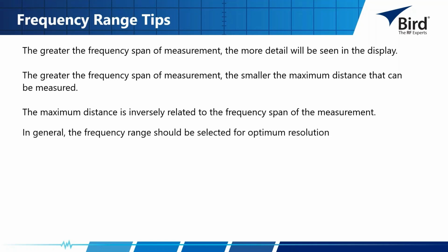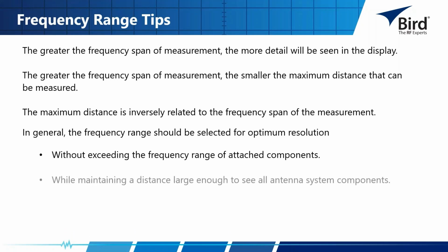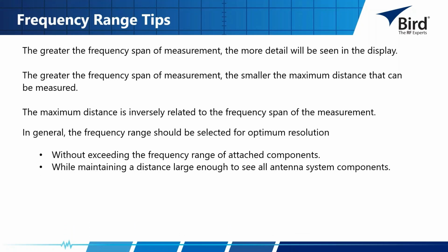In general, select your frequency range for optimum resolution without exceeding the frequency range of the attached components, and while maintaining a distance large enough to see all the antenna system components. And add approximately 10 to 20% to the known cable length.